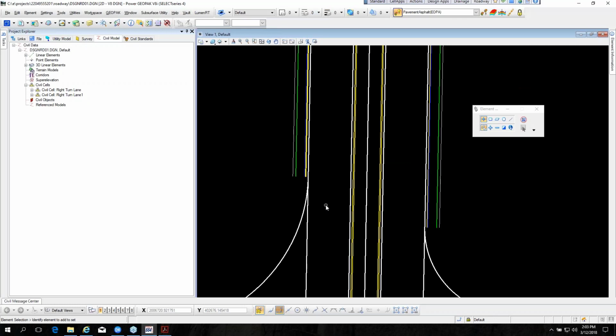To turn that back. The other problem I think is when we adjusted that to 0 it was putting two lines on top of each other, and we weren't picking the right line, because if you remember, it's how it was built. So it did this line, and then from this, your edge of your back of curb is a parent of your front sidewalk. So since we changed that, we were trying to change the child before we changed the parent. I believe that is how those were working in there.